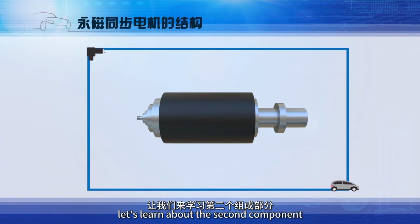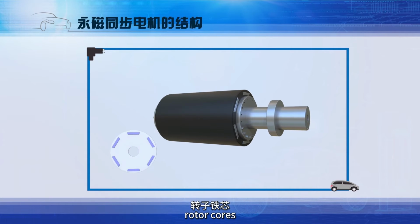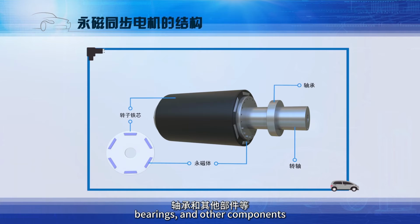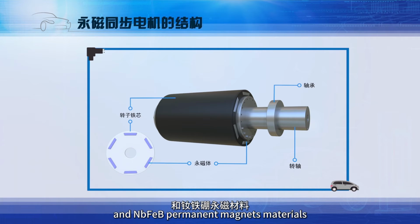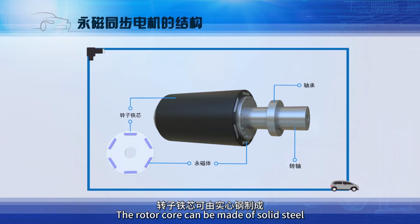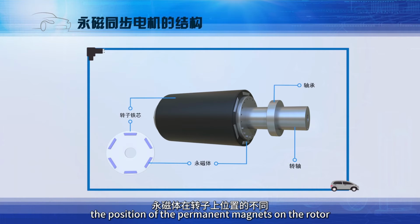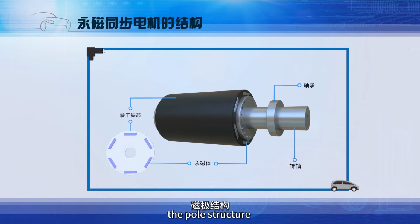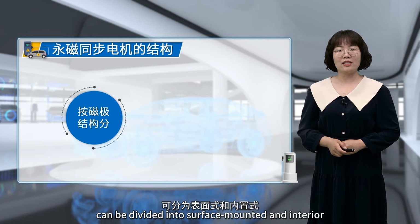Next, let's learn about the second component, the rotor. The rotor consists of permanent magnets, rotor cores, shafts, bearings, and other components. Permanent magnets are mainly made of ferrite permanent magnet and NdFeB permanent magnet materials. The rotor core can be made of solid steel or laminated silicon steel sheets, depending on the pole structure. According to the position of the permanent magnets on the rotor, the pole structure of the permanent magnet synchronous motor can be divided into surface-mounted and interior.